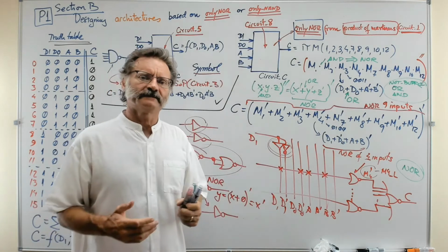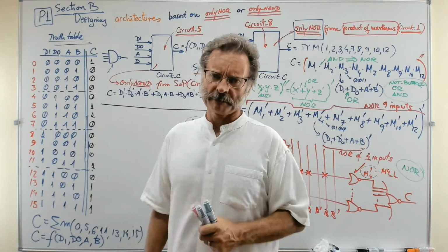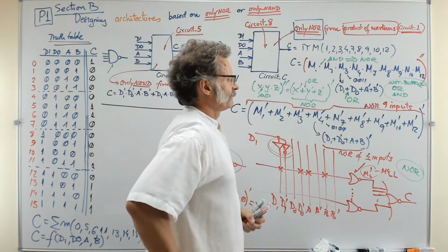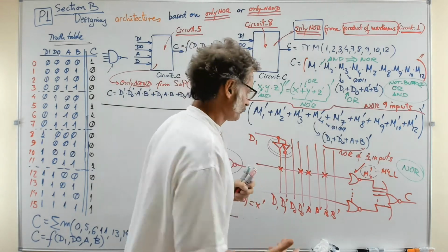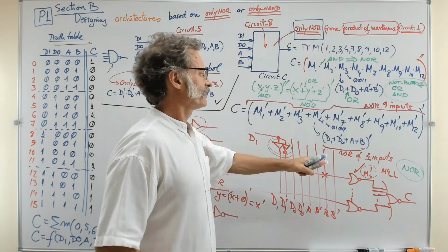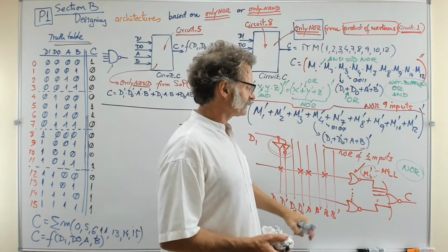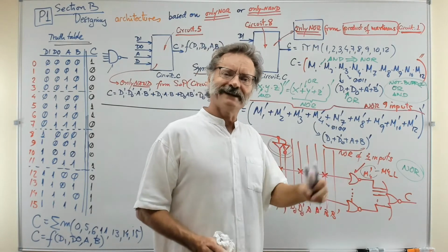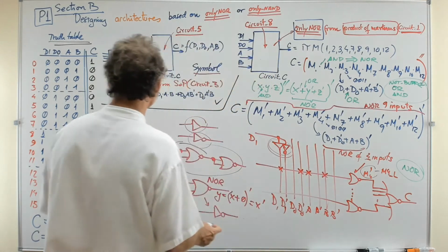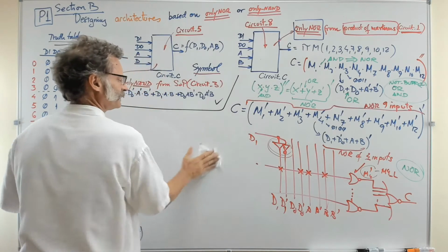Okay, and then there is a last example if you'd like to complicate things a little bit. There is another constraint that we can discuss here, but it is not going to be difficult. You can expect this other question. What if I ask you now to invent a circuit based on only NOR, but where all the NORs have to be NOR 2? How can you do that? Well, that is perhaps the last example.